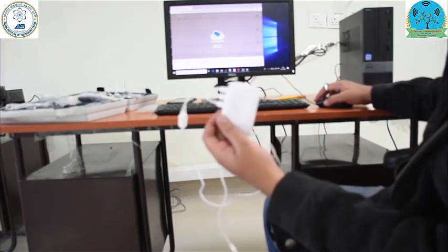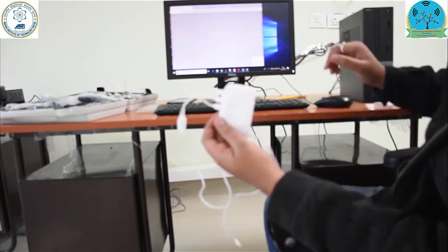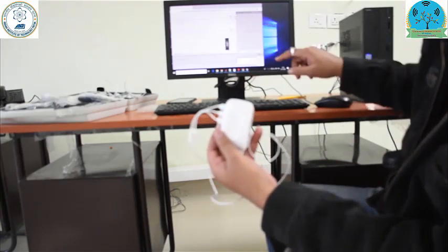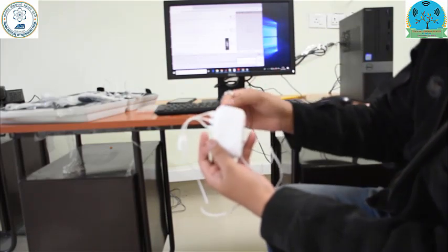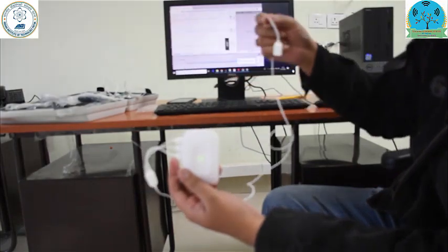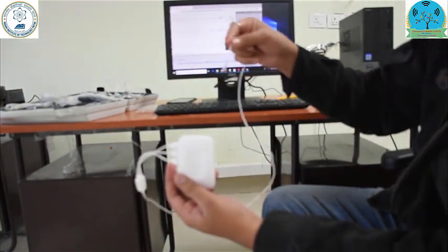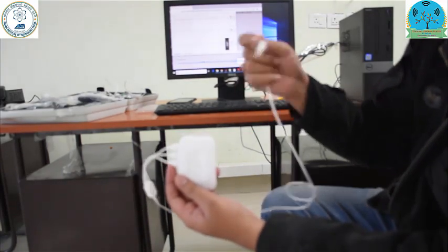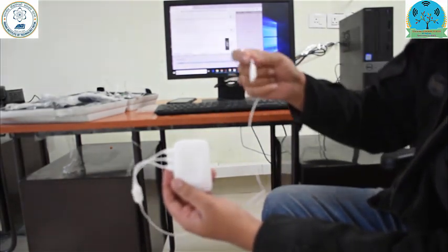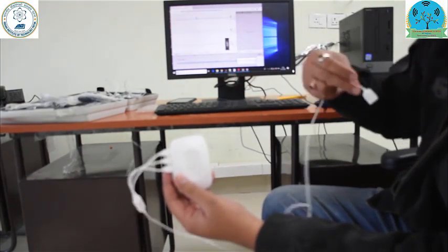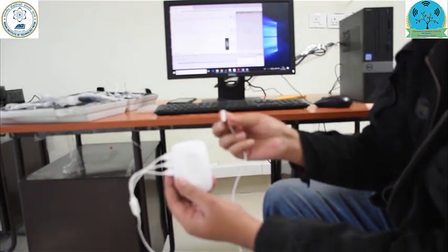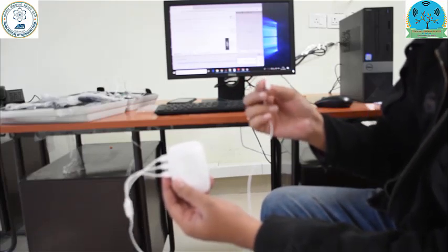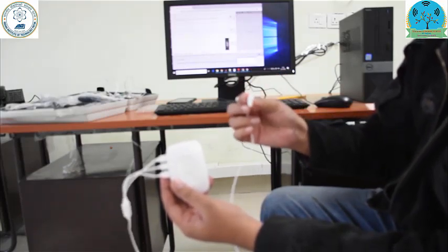So I have enabled 3 channels here, and the file viewer clearly shows the 3 channels, that is 1, 2 and 3, and you can see on the screen there is not much activity. But when I start rotating this sensor, or when I start moving this sensor in the directions, and increasing the acceleration, you can clearly see an activity on the screen and the data values are changing. So the sensor is very much able to measure the acceleration in all the directions, and as I slow down the acceleration, you can see on the screen also there is not much activity happening. This all data is recorded digitally at 700 Hz with 16-bit resolution.